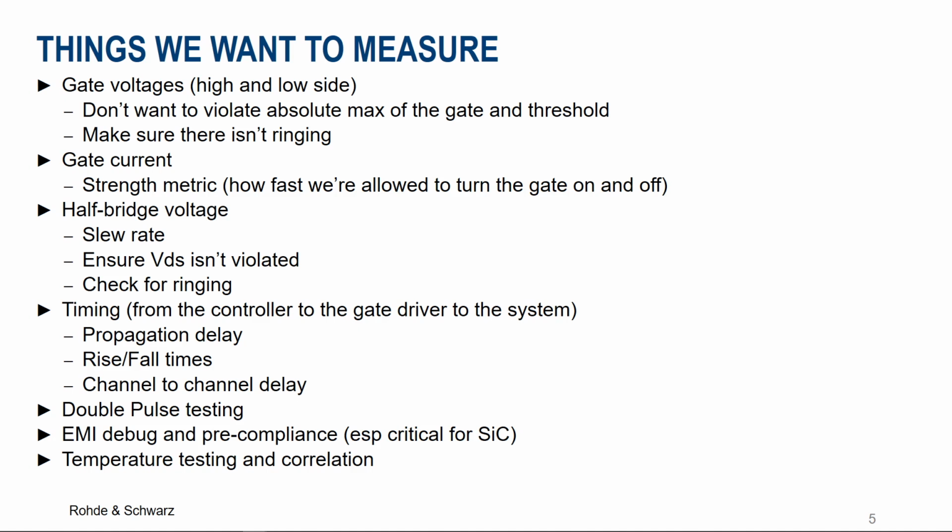There are many sources of noise, including CMTI, input glitches, and RF noise in and out of the system. When possible, evaluating radiated emissions is important. Testing is accomplished through proper EMI compliance testing, which will be discussed in this presentation.